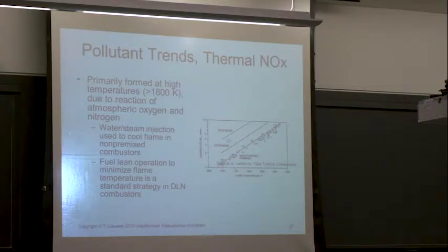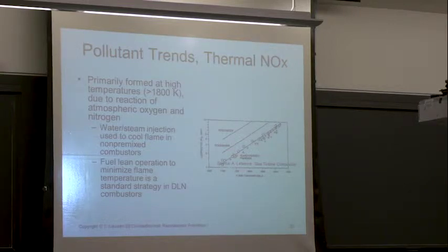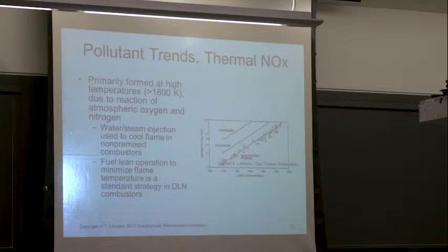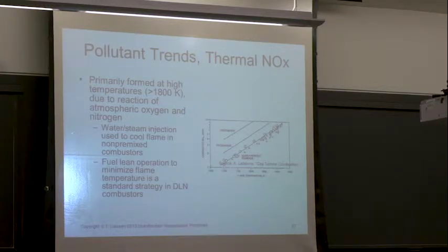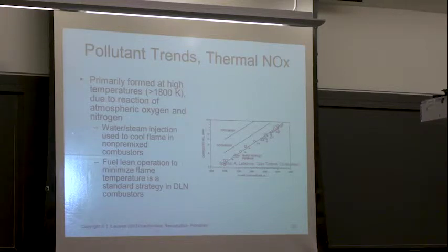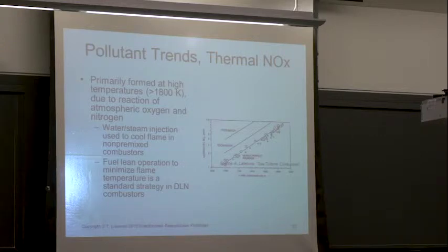But what they also have are lines that show mixing quality. So the idea here is that this is if you really have nearly perfect premixing. And that, by the way, gives you a pressure drop, right? Better mixing means it's going to take more pressure to shove your fuel through these. You're going to need smaller orifices, more distributed fuel, more turbulence, and all that stuff gives you pressure drops, which gives you a cycle efficiency hit.